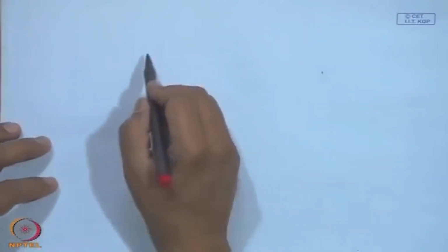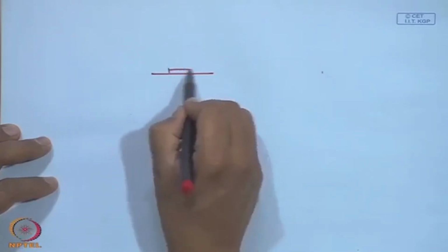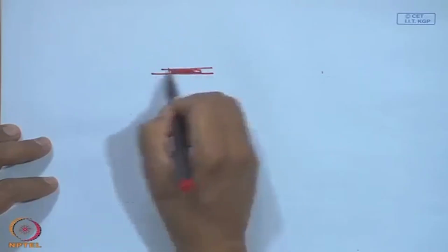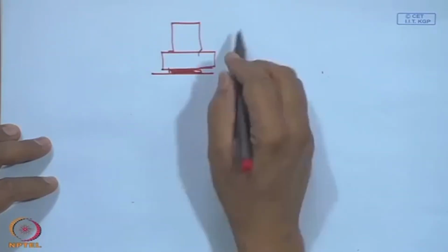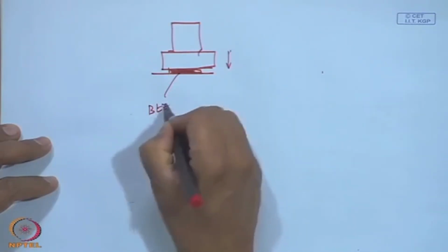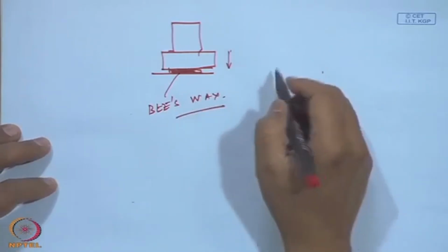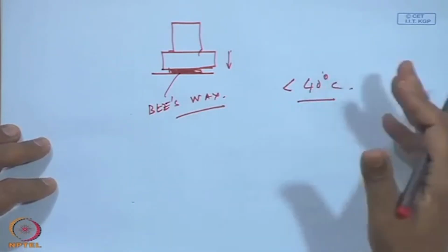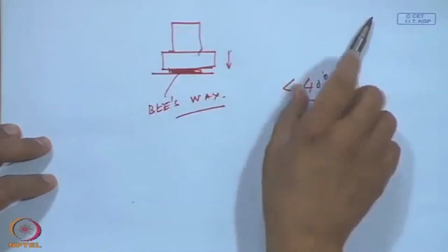But sometimes even just a layer of beeswax on a surface, the honey beehive beeswax. You can just put it here and then stick the accelerometer onto it. Okay. Just press it, and this is the beeswax. They are pretty strong. But the problem is you cannot use them beyond 40 degrees. In room temperature, these are good, but beyond that they will melt.